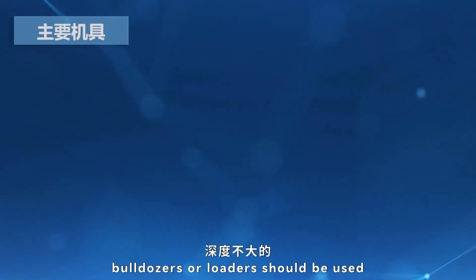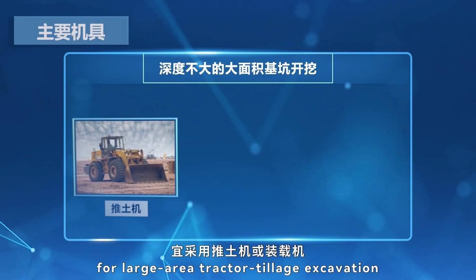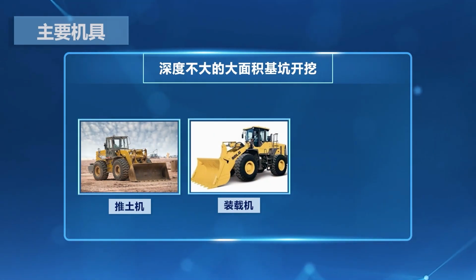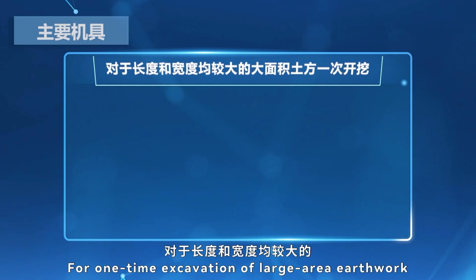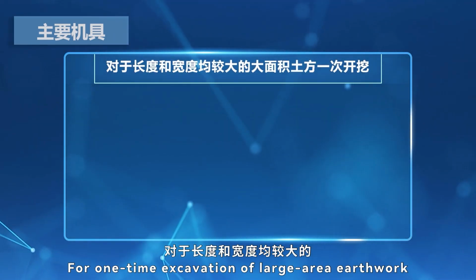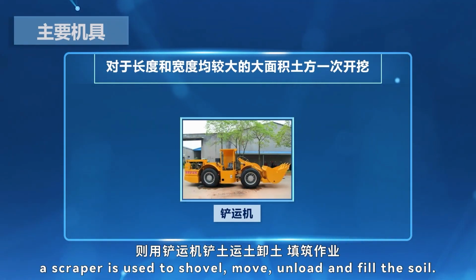Generally speaking, bulldozers or loaders should be used for bulldozing and loading for large area tractor tillage excavation with small depths. Use dump truck to carry the soil. For one-time excavation of large area earthwork with large length and width, a scraper is used to shovel, move, unload, and fill the soil.